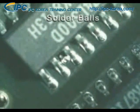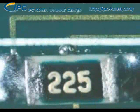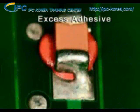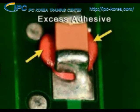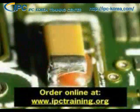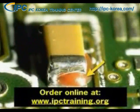Any balls of solder that are not entrapped within a permanent coating or attached to a metal contact or violate minimum electrical clearance requirements are also considered defective. Any adhesive material in the termination area is considered a process indicator for Class 2 and a defect for Class 3. Adhesive causing less than minimum end joint width is considered a defect for both classes.